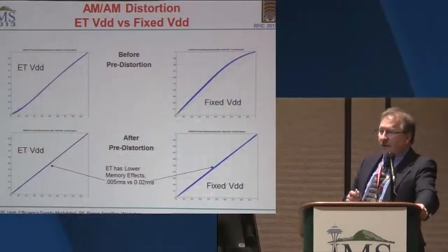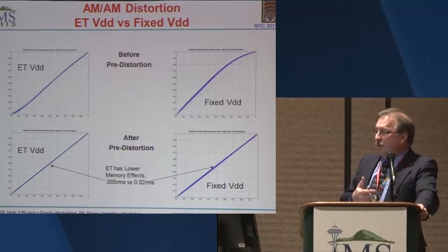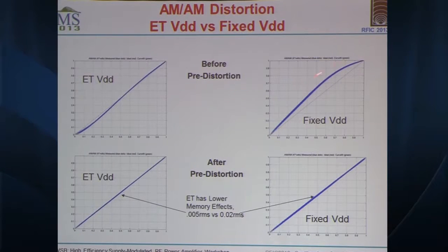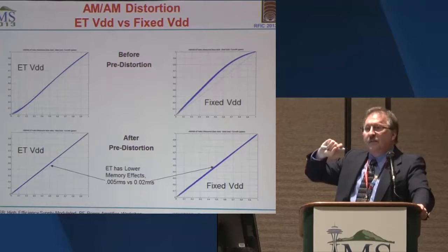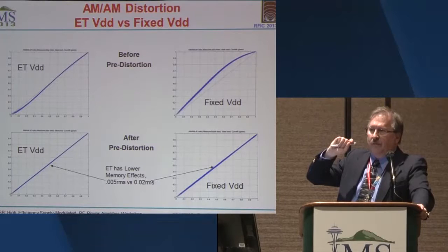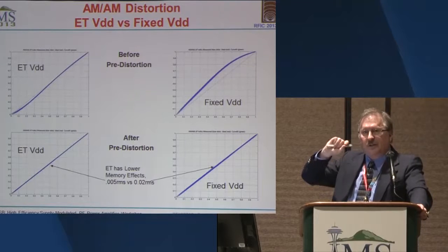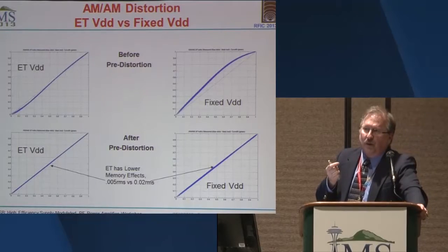The DPD, this shows how we've taken the DPD that I've talked about earlier and applied it to envelope tracking, and how it's a little bit different. The first thing you'll notice is that the AM to AM curve from fixed VDD to envelope tracking is very different. As someone noted earlier today, you can pick a trajectory in the VD, VN space to have different features. I believe it was the gentleman from Skyworks who said he selected in one case a constant gain trajectory. Professor Larson conveyed an approach that we typically take at UCSD, which is optimal efficiency.